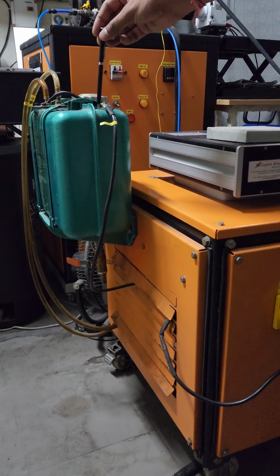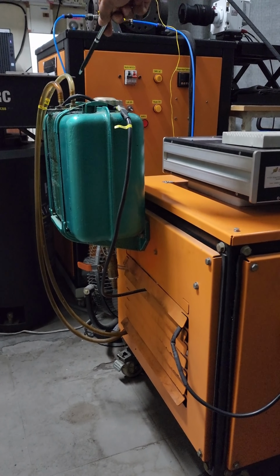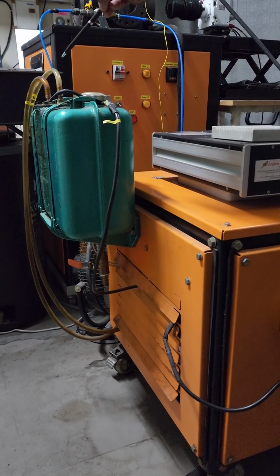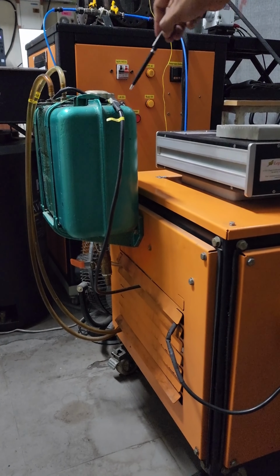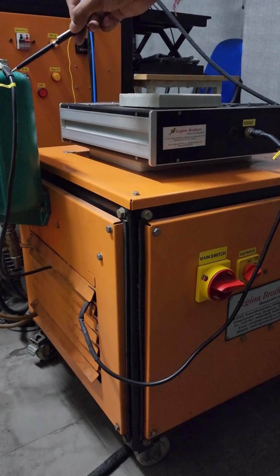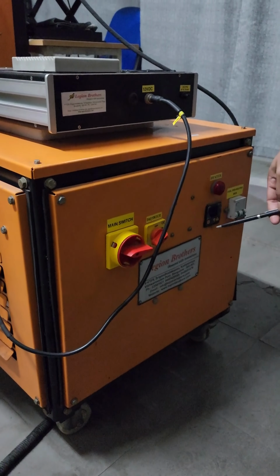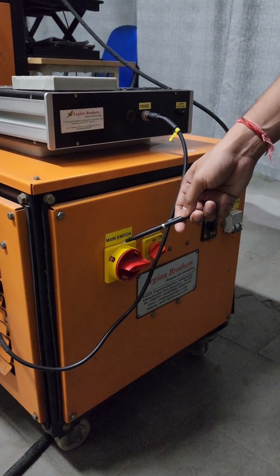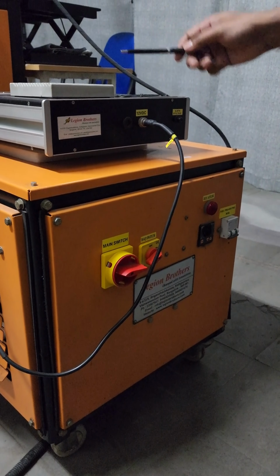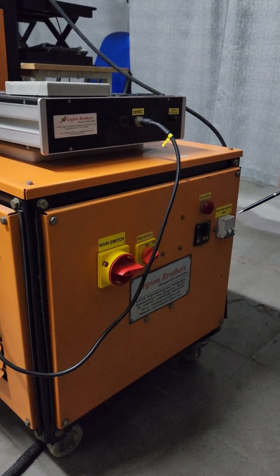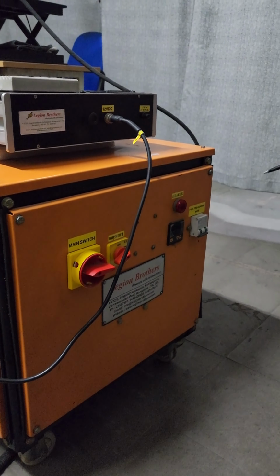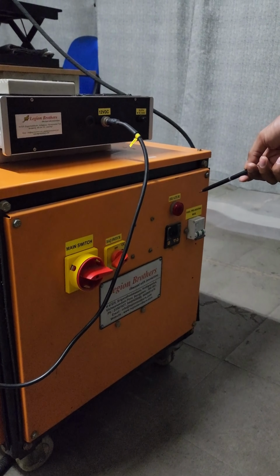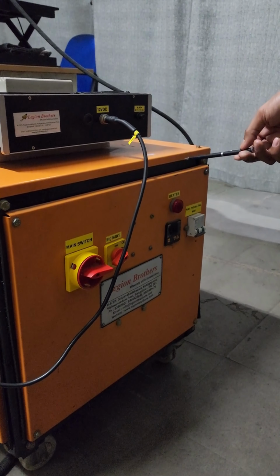This is the fuel tank, and we have 2 lines, the outlet line and the inlet line, or the backflow line. This entire system is operated first through the main switch, and this ECU is operated through this switch. We can also heat up the fuel. Inline heating of the fuel is possible with this existing system.